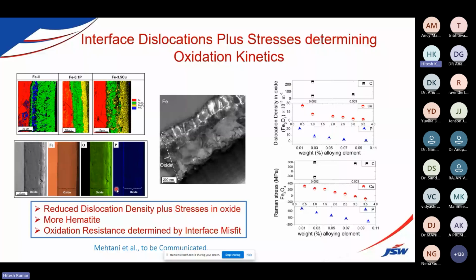We also looked at the oxide microstructure. You can see a columnar growth structure in the magnetite grains, and there is some retained wustite, where the reverse eutectoid transformation could not take place at those particular points.